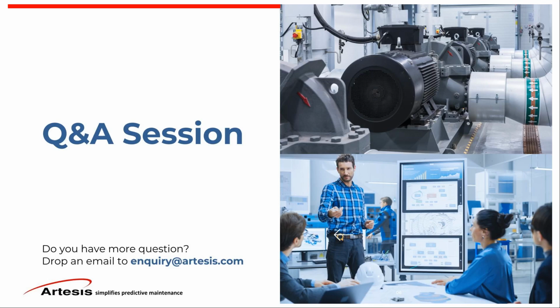However, the spectrums that are captured are processed internally in the device, but the result of those spectrums, I think that's what you're referring to with this question, is how often it is updated. At default it is every 10 hours, and the trend data is every 15 minutes. The reason for that is we try to optimize the database storage because we use an SQL database. But if you want, you can make it one iteration, which is equal to 1.5 minutes. So you can update the spectrums every 1.5 minutes, but that will unnecessarily fill the SQL.